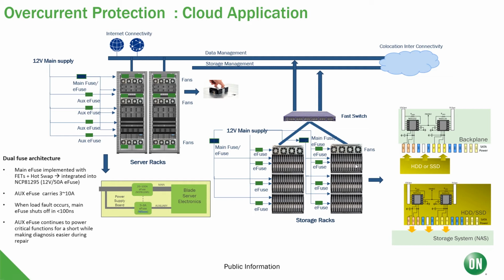Finally, on the right-hand side, you will see the hot pluggable SSDs and HDDs that require eFuses for inrush current protection, as well as reverse current blocking for safe shutdown. Not only do the memory devices require eFuses, but the backplane requires protection from a bad drive being hot plugged into it. Okay, moving on to other key applications.